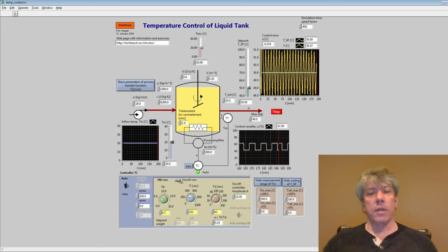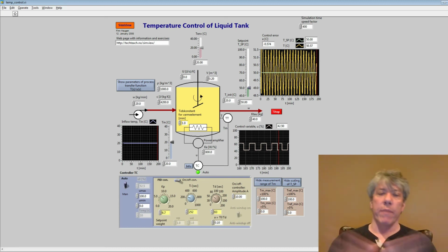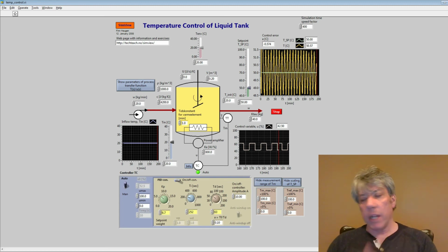Now remember, with the Ziegler-Nichols method, I got an ultimate gain of about 10.3 or so. And you might say, well, there's a difference there. Yeah, there's a difference. Controller tuning is often not, I don't want to say it's not precise, but it gets you in the ballpark. And so often it won't matter that the ultimate gain we've gotten here is not exactly right. If you were to just go in blind to this scenario, you'd have no idea whether your ultimate gain was going to end up being 0.01, 0.1, 1, 10, 100. You wouldn't even know the order of magnitude, right? There's this entire range that you could traverse before you even get close. So relatively, 8.5 and 10.3 are relatively close to one another. They're reasonable numbers and reasonable measures of this system.